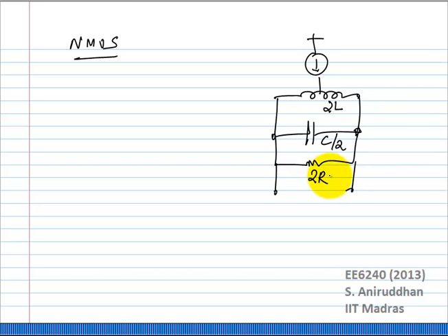That is because I actually took LC and RLC on either side. I didn't consider it as a center tap. But suppose I do consider it as a center tap, I need to use twice the inductance. It is going to use twice the area. What is one easy way of handling this?